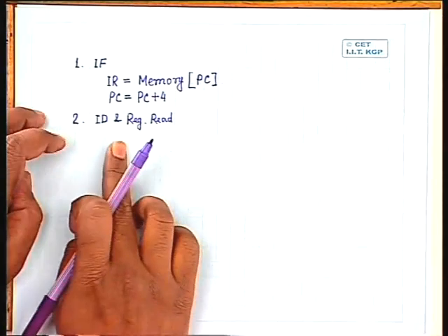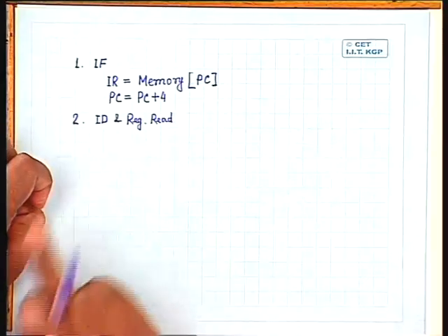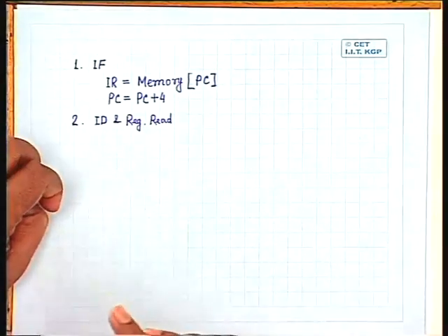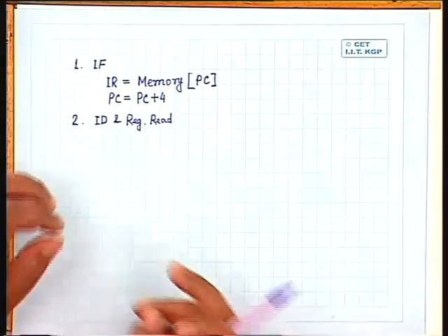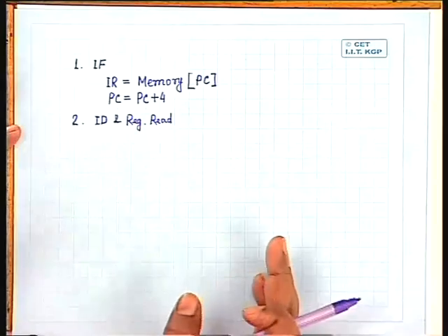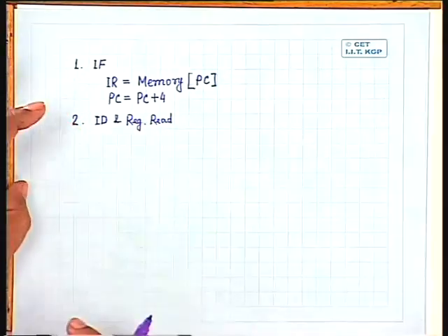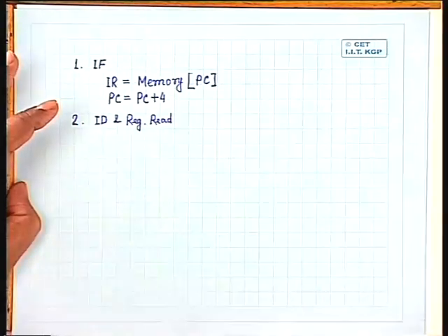Okay. So register read is such an operation. If I read the register and put the output of the register in, say, intermediate registers A and B, that is not harmful. Maybe the data that is read will not be used, that will be overwritten by fresh data during later clock cycles, but this is not harmful. So we can read these registers.